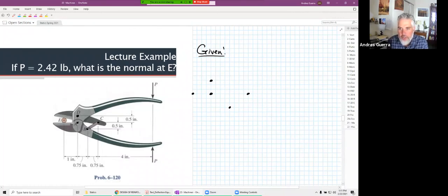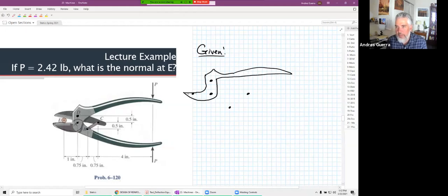Then we can start to draw our rigid objects around those. Like this bottom jaw, let's draw this bottom jaw to the top handle. So this bottom jaw goes like this. It does go around these 2 points here. And then it wraps back and we have this top handle here. And so really, then it becomes less of a focus of, do our rigid objects look good? It's more about, do our rigid objects include the correct points that they need to include? So that's one rigid object.